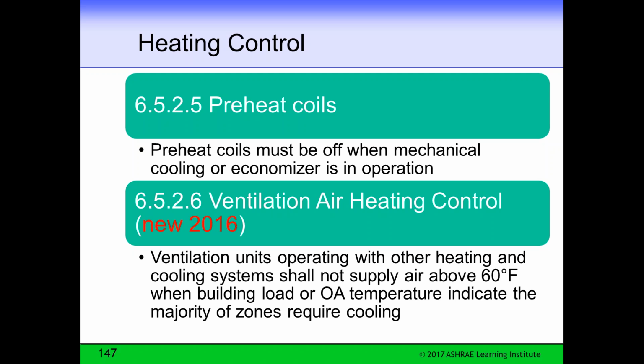Then we don't want you to do exactly neutral air. Since you're cooling the air down to dry it out normally, we want you to go ahead and supply it at 60 degrees to the room. That would cause your normal air conditioning system to back up a little bit, and we would take advantage of that colder supply air. Normally DOAS systems will come in at exactly the thermostat setting, 72, 75, some number like that.